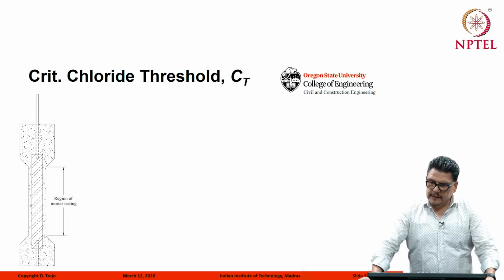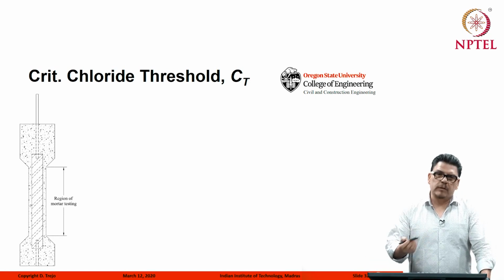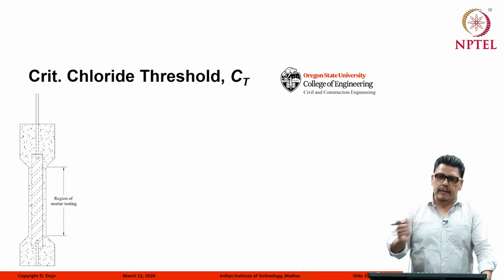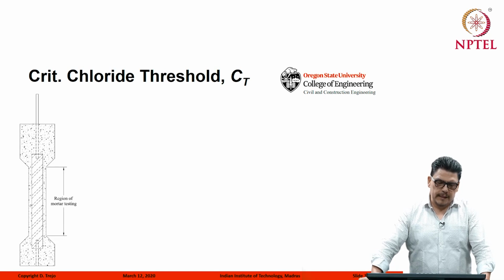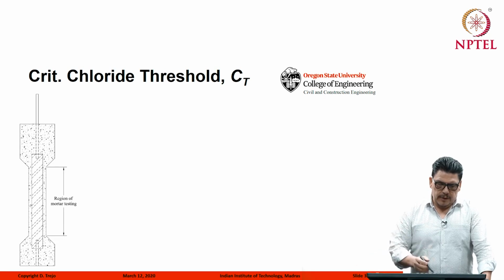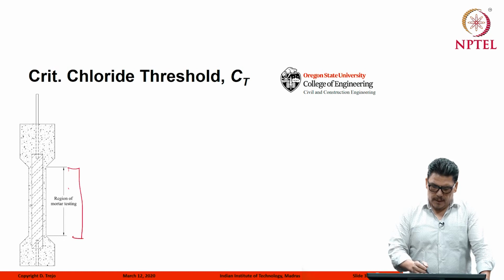Okay, so if we look at this region here, we crack this region off and expose it for some time, and typically the test can be done in about 4 to 5 weeks. We cure, and then we expose it 4 to 5 weeks, no more than that. And you can see the region of mortar testing is here, from here to here. It easily breaks off the sample.